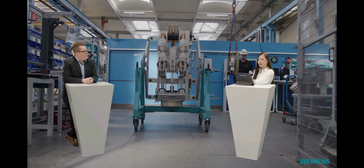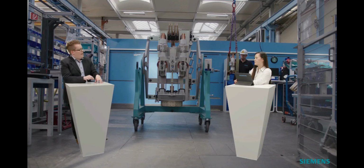Okay. Is it able to check the DC components also in the estimation tool? Unfortunately, this is not possible because to check the DC percentage, we have to know the detailed generator data, because the DC percentage is calculated due to the transient behavior of the short circuit current. And as I've said, the transient behavior cannot be covered by the estimation tool. That's why if you contact us with the generator data, we can easily calculate the DC percentage and present it to you.